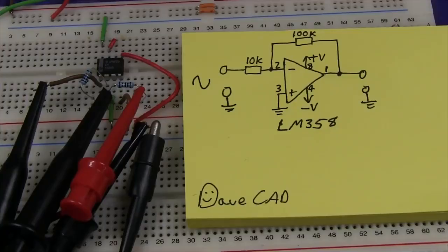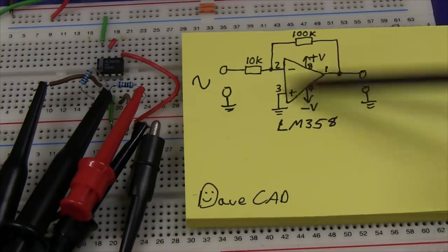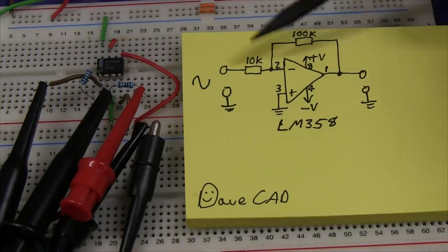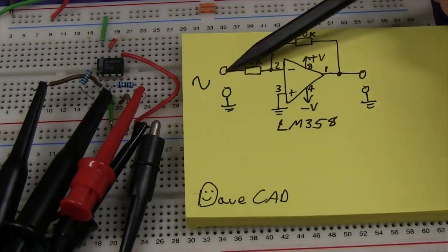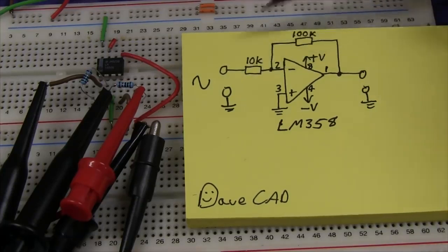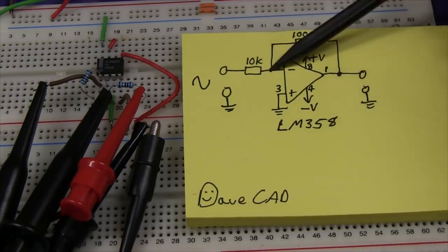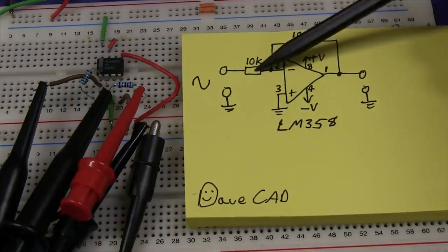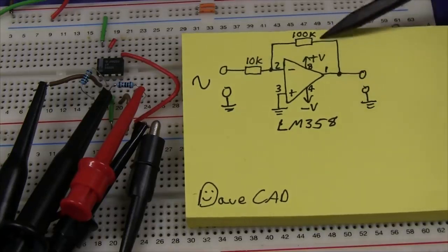But of course, you know it's not magic. It's just standard op-amp behavior with virtual ground on the input. That's how an op-amp works. And no, the current hasn't magically vanished. The current is going through the resistor. Ohm's law still holds. Current is changing because we've got an AC resistor here. There's AC current flowing through this resistor, and it's all flowing up here.